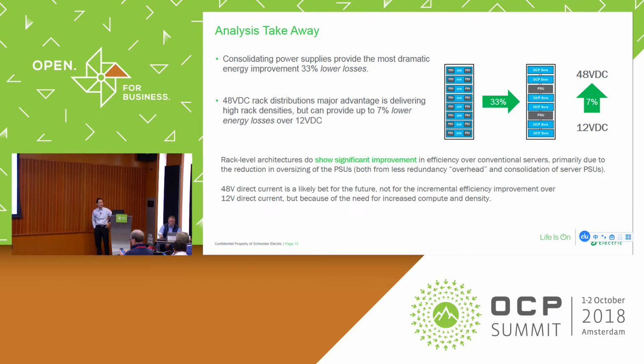Hi. Two questions. One is, in your calculation, do you assume distribution losses to be the same or better for 48 volts? Which kind of distribution loss? Through the bus bar, through the clip, through the connectors? Because when you're doing 48 volts versus 12, I assume the distribution losses will be way less. So through the entire bus bar, if the length of the bus bar is 2 meters, through each clip, each connector, I think you have extra efficiency savings there.